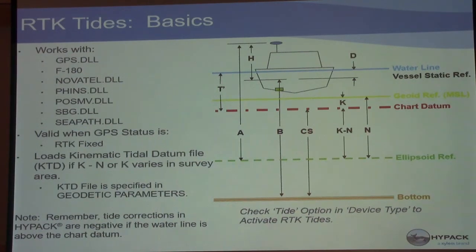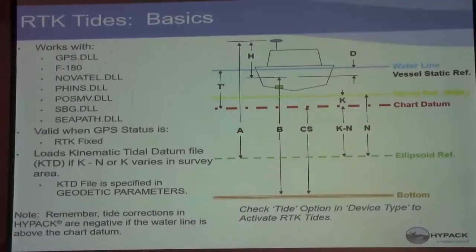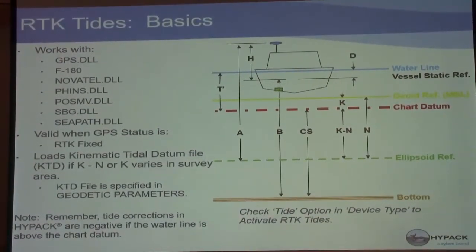Okay. And typically, it's been set up in HYPACK where the only time you're actually going to get RTK water levels is when you're in RTK fixed mode. There's been a source of contention about that for many years, because a lot of people are saying, you collect the raw data. Why don't we collect everything, and then I want to be able to filter that out after the fact? So there are ways of getting around it, and as we're constantly updating device drivers and things like that, as we go along, more features. Sometimes that's good, sometimes that's bad, as most of you guys know.